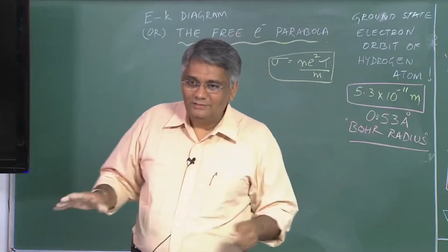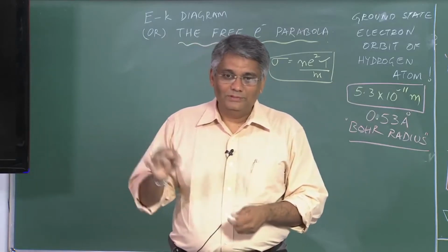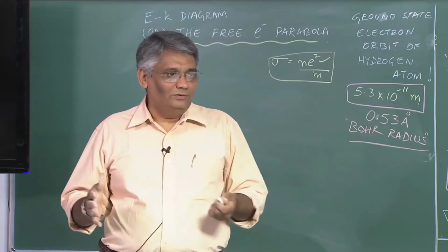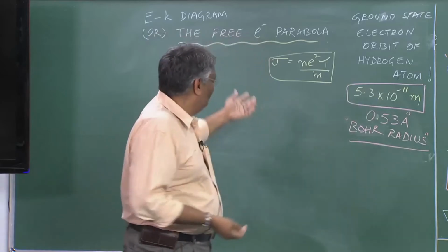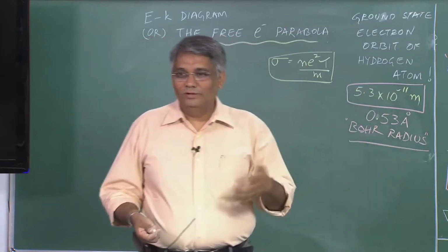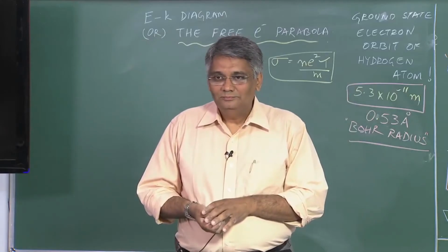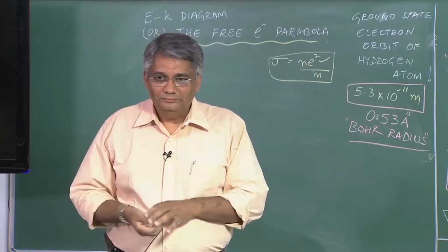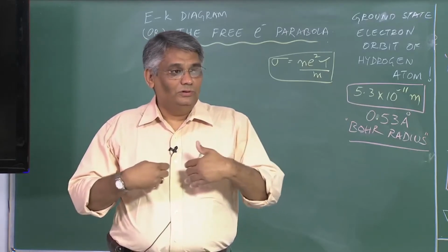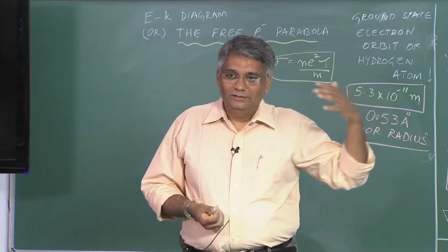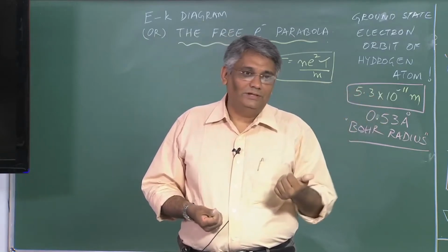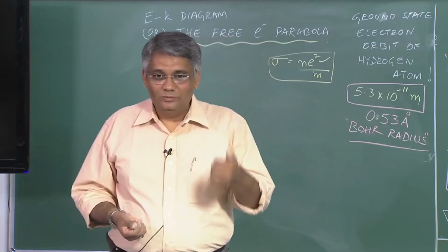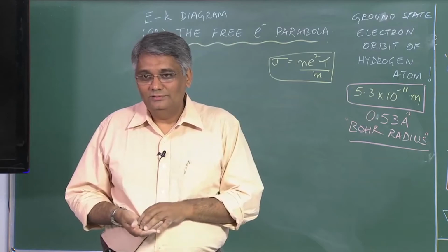So in metallic systems we don't talk about the presence of holes. It's always electrons, free electrons, right? There are always conduction electrons, plenty of them, a large number, 10 to the power of 28 to 29 per meter cube. Now you can increase the electron density in a semiconductor by doping. Remember I gave you some numbers, the conductivity can be changed by almost 4 to 5 orders. The electron density can also be changed by 3 to 4 to 5 orders.